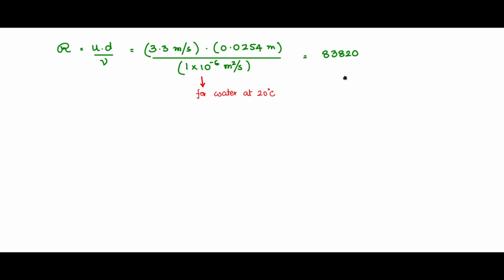You have to use the Colebrook-White formula for this. We have already done that exercise and have the function for that in Octave. You can use that function readily. So before that, calculate the roughness ratio. Epsilon, which is the height of the surface bump for PVC, is 0, and therefore epsilon by d, the roughness ratio, is 0.